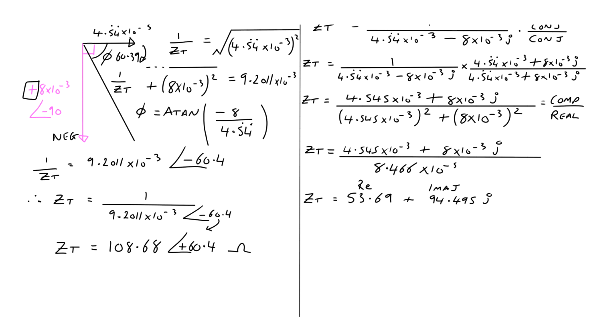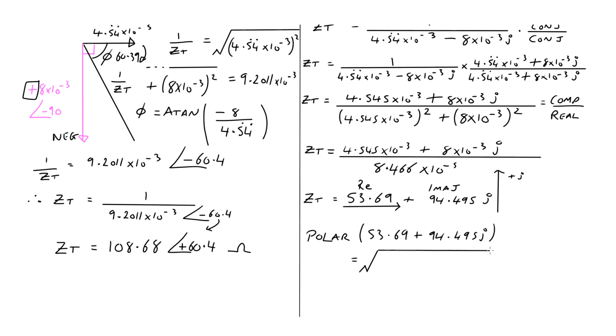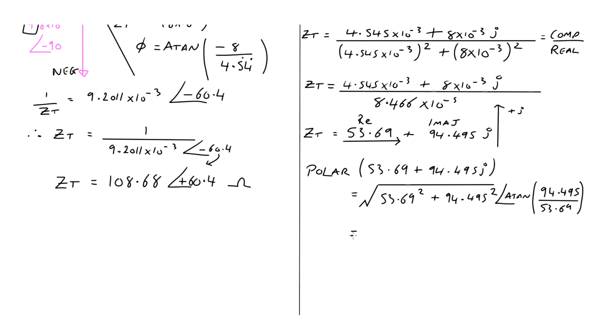So they are equivalent to each other in polar and rectangular, hopefully, but we need to convert one to the other to check that that's true. So we'll convert the rectangular version into polar using Pythagoras and tan to the minus 1. So adjacent squared plus opposite squared at an angle of tan to the minus 1 opposite over adjacent. So it's pretty simple, really. It's just about triangles.